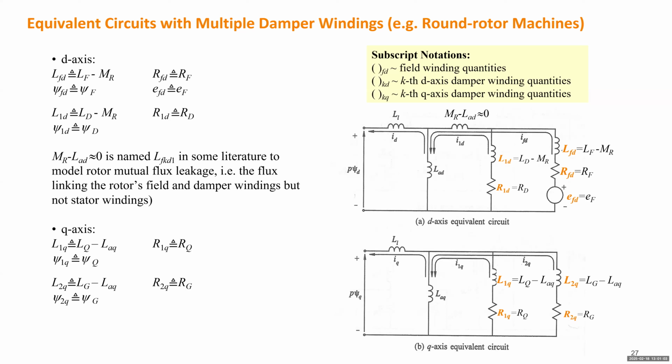We're going to show that this equivalent circuit came from those two circuits by simplifying some parameters. For a transformer, it's also not convenient to have two circuits, one for the primary winding and the other for the secondary winding, which are isolated. So you want to connect the two windings into the same circuit. Having just a single circuit to do the study is always more convenient.